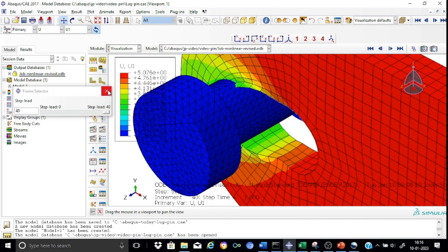So this is all regarding the deformation behavior of the lug, and we come to the conclusion that the lug has yielded and the bolt is strong enough. There is no problem as far as the bolt is concerned, and the deformation response, the contact and the von Mises stress distribution reveal that Abaqus has properly modeled the contacts and the interactions between these surfaces.